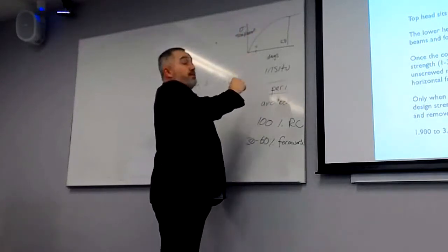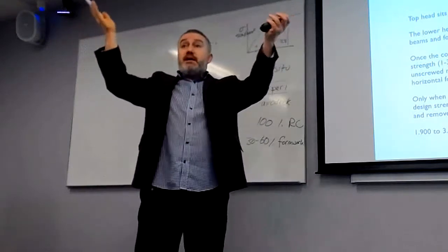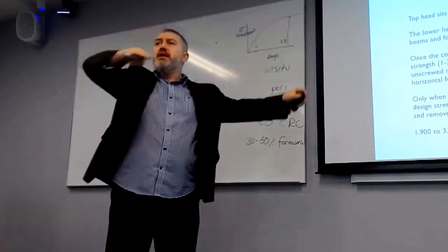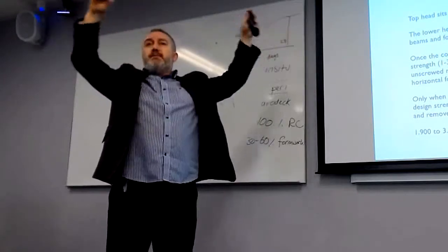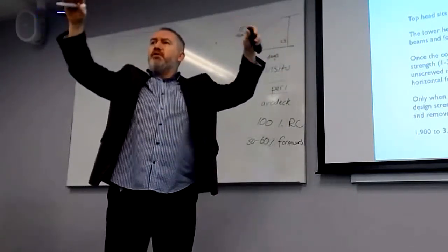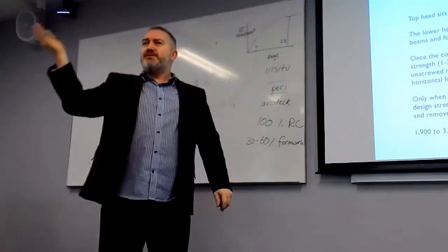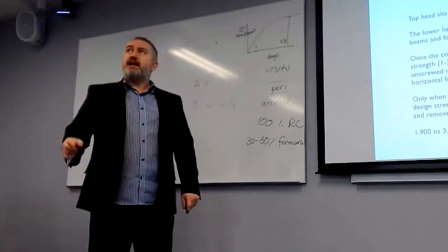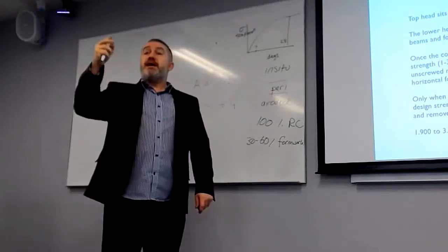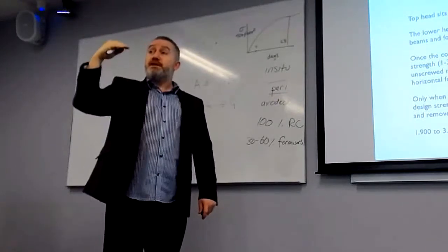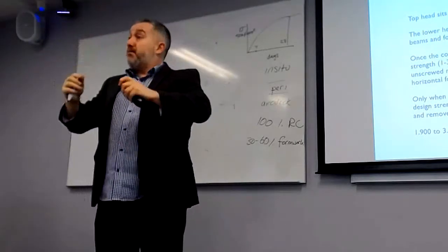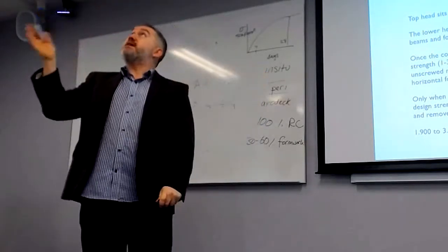But we don't want to keep this formwork in place for 28 days, because if we were doing a floor with the same formwork, we'd be doing a floor every month. And if it was 12 floors, it would take a year to do. So contractors find out when you can remove the timber from the concrete, because if you pull the timber away too early, it pulls away the surface and just wrecks it.